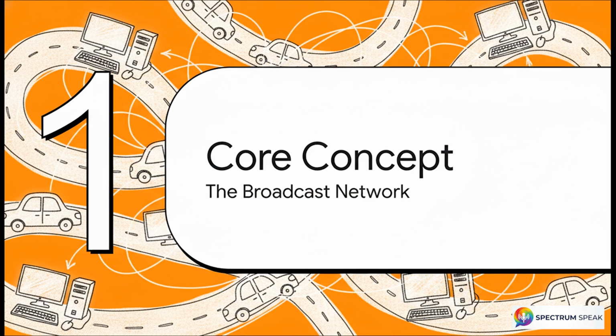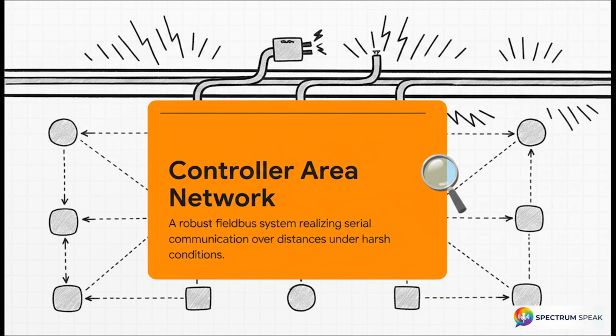Section 1. Core Concept: the Broadcast Network. So you might be wondering, how exactly does a shared highway not immediately devolve into absolute chaos with 50 computers trying to yell at the exact same time? Well, by definition, CAN is a field bus system realizing serial communication. But what actually makes it special is that it's engineered to work flawlessly over larger distances and, crucially, under highly unfavorable electrical conditions. We're talking about the crazy, electromagnetically noisy environment of a running car engine. And, unlike older centralized networks where a single master computer bosses everyone around and dictates who speaks, CAN is entirely decentralized. Every single node on the cluster is an absolute equal.